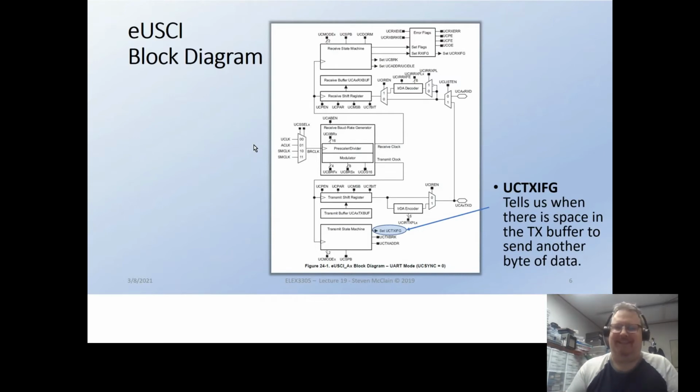It's great. It's a little tricky, but it's great. What happens with that is you end up setting up, say you wanted to transmit 100 bytes out the port. Well, with DMA, you can basically say, okay, there's 100 bytes over there, serial port. Send them and let me know when you're done. That's effectively what you get. You get one interrupt at the end of the 100 bytes. That's when you're doing it right, that's what you get, but it's tricky to get there, and you're a ways away.